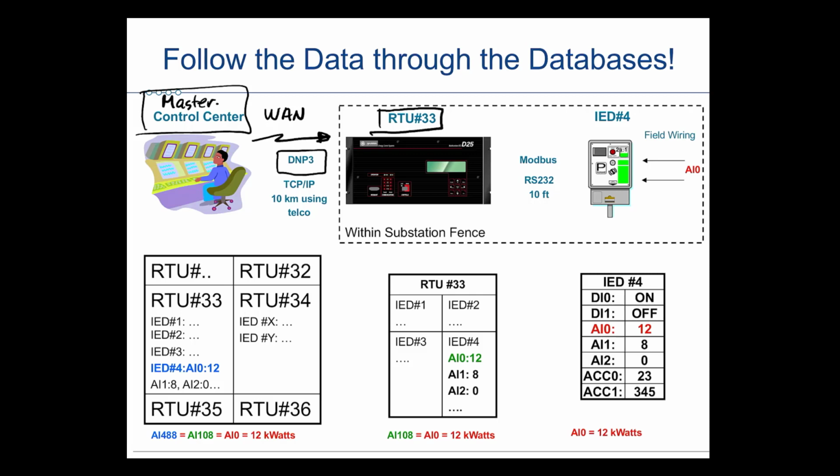So if we look locally at that site, what we have is Modbus as the master-slave connection for the RTU to be a master to the local area network, sending out a request to this IED. Remember, that stands for Intelligent Electronic Device. And notice how it's got a unique identifier as well on that local area network, IED number 4, sending out a request and obviously waiting for that response, and then moving around to all the other IEDs in its Modbus network.